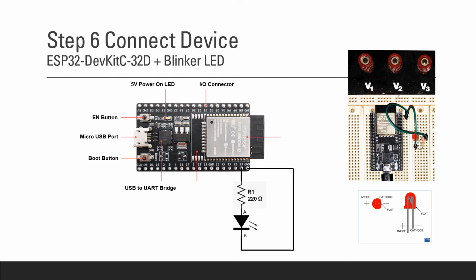Now, let's spend a second on the hardware, which I've discussed in earlier blogs. In this one, we have to add in an LED to turn on and a resistor. So I've shown it schematically here. We're going to hook it up to the pin labeled 23. That's IO number 23. And so we have a 220 ohm resistor and a run-of-the-mill LED going back to ground.